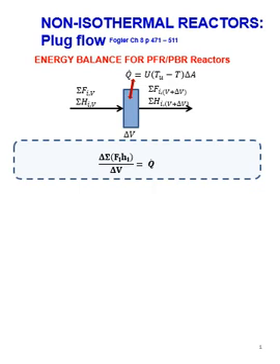So when I consider the energy balance of a plug flow reactor, just as when we derived the mole balance, we are going to do it over a small slice of volume of that reactor, where the sum of the change of enthalpy of my flowing streams in that little volume is equal to the amount of heat transfer from that small slice.